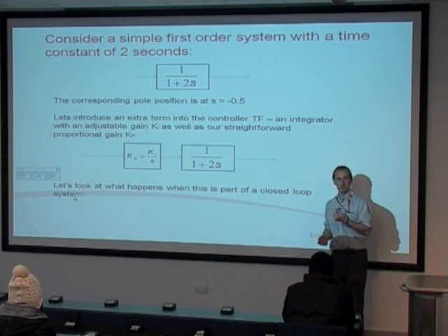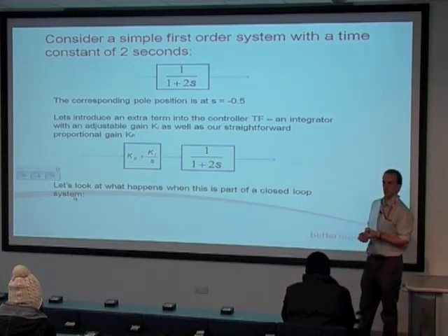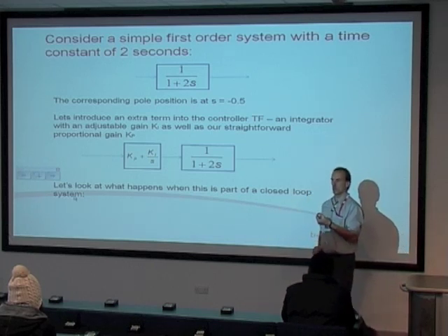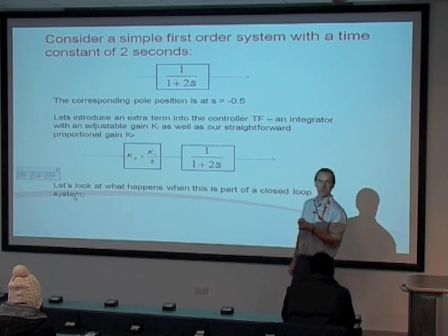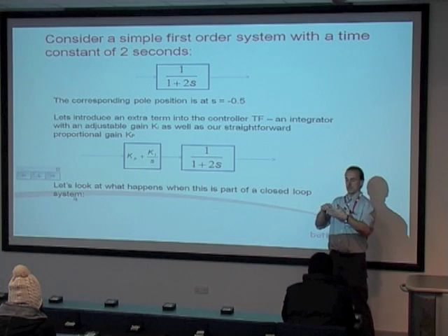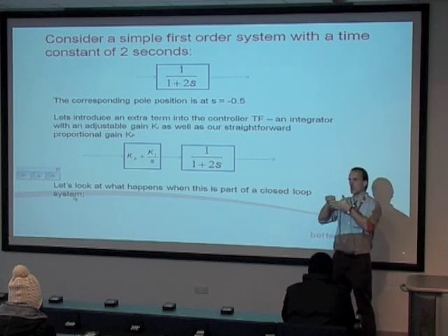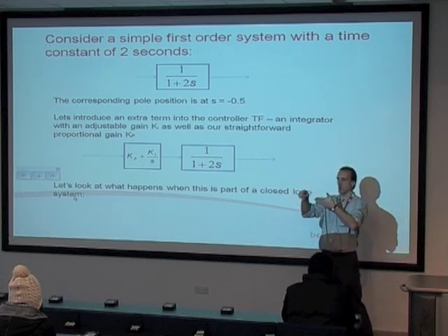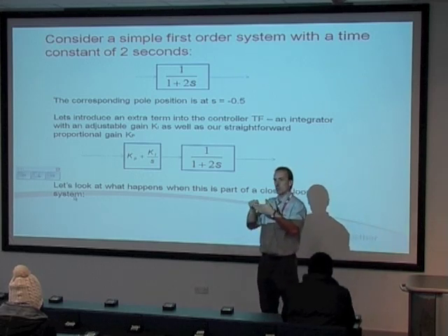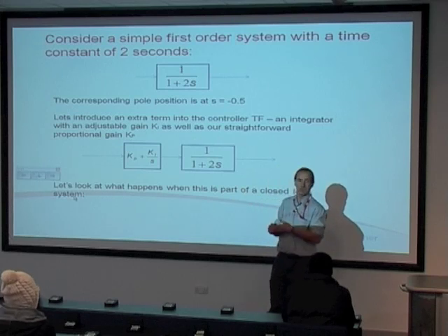So I've got a signal which I call the error signal, and I use that signal to drive, let's say, a motor that works the throttle pedal or works the throttle butterfly. Okay, so if I'm too fast, then the negative feedback will come out negative, and I'll unwind the throttle to slow the car down. And if I'm going too slowly, then the error signal is positive, and I'll wind the throttle open.